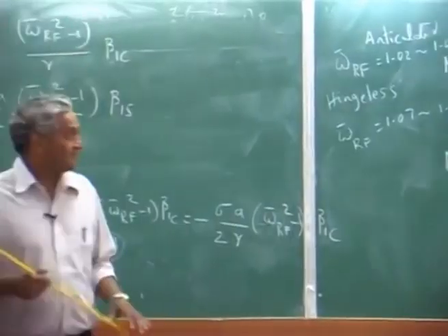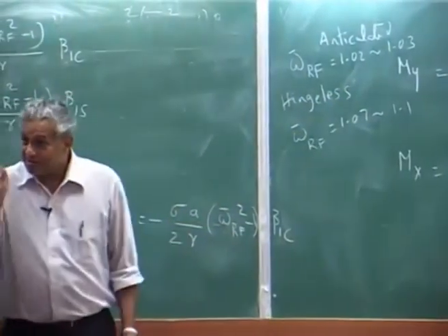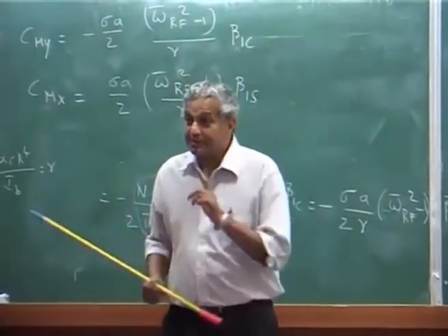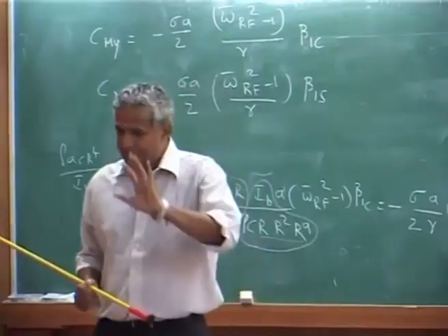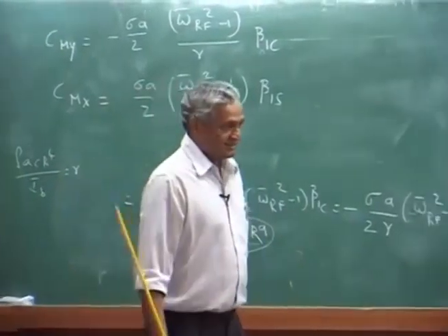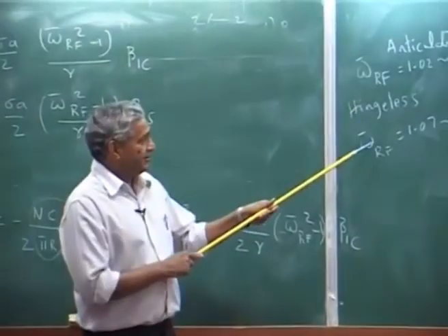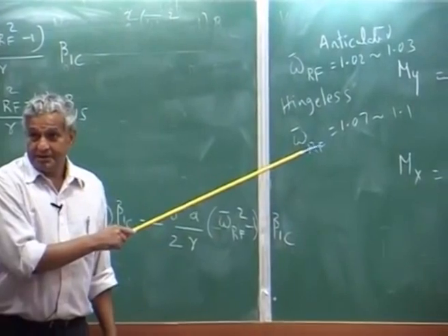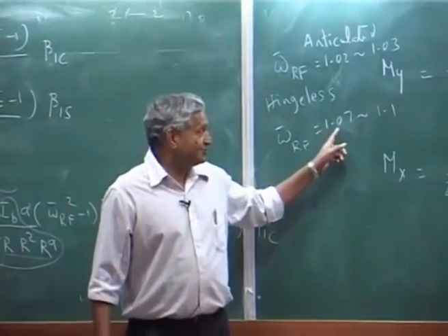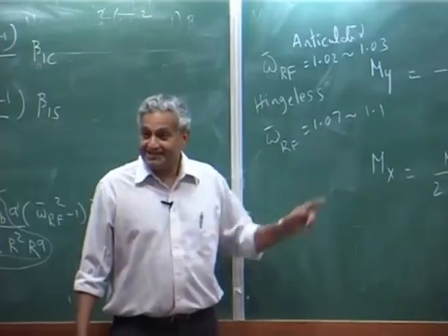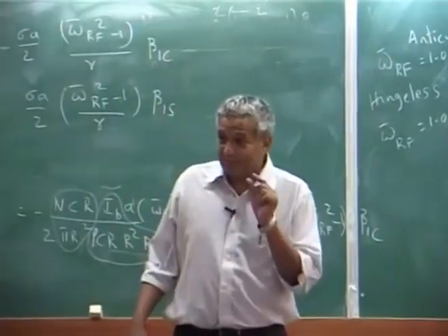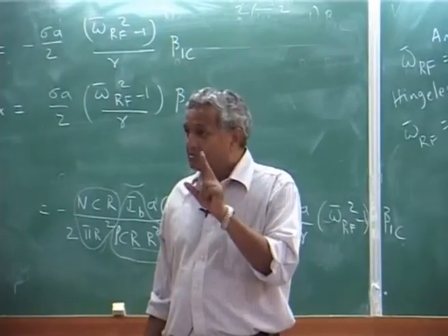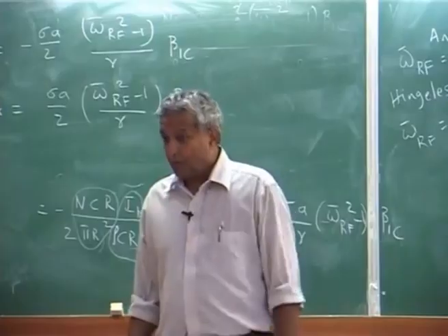Now, you see articulated rotor, because you have a hinge, but you do not have a spring. So, the model is a little different, that part you will learn when we do the next section. You see the flap frequency difference, this is a high flap frequency. That is why I am saying I have written up to 2 decimal points. Industry will calculate, you will be surprised, they will want to go to at least 2 to 3 decimals in flap frequency. Why?